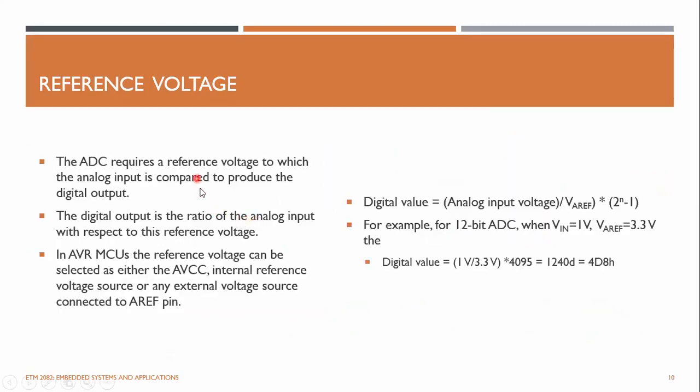And the reference voltage, I have shown you in the microcontroller, there's a reference voltage pin. So definitely you need to have a reference voltage when you're doing the ADC. The ADC digital output value is the ratio of the analog input with respect to the reference voltage. Okay. So either you can select the AVCC voltage or the internal reference source, bandgap reference, or any external voltage source connected to the AREF pin.